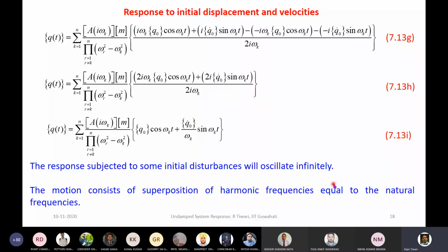In the video lecture I sent regarding the lab, if you look back at it, you can appreciate how we can obtain the natural frequency of a beam, or a beam with two disks or three disks, using the so-called fast Fourier transform. Directly through the instrument, we can see them.